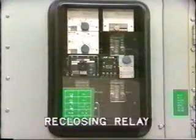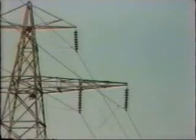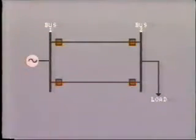One way around this problem is to bring the line back into service again as quickly as possible by automatic reclosing of the breakers. This action is based on the fact that most faults on overhead lines are temporary faults caused by a lightning strike or high winds or other climatic conditions. We have already discussed this in earlier tapes. When the breakers are reclosed after, say, half a second, in most cases, the temporary fault will no longer exist.